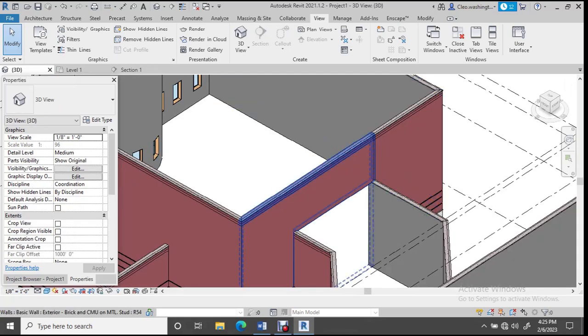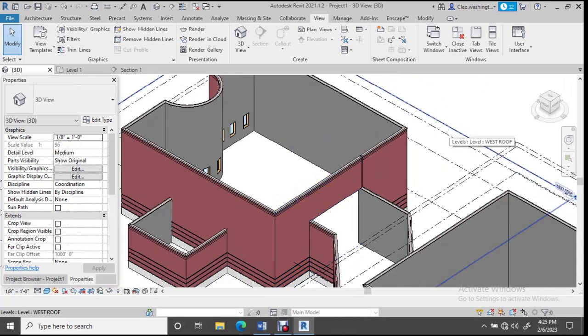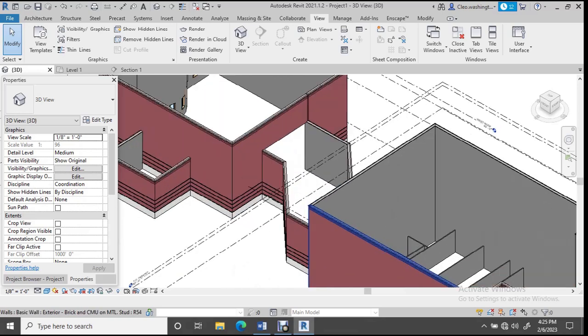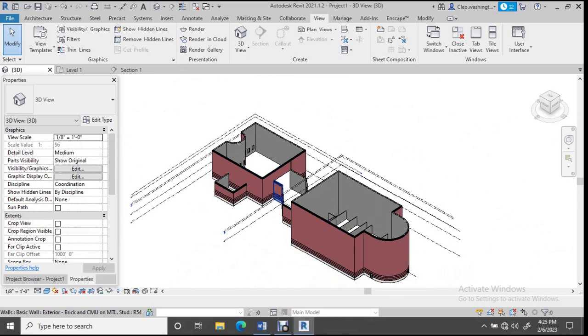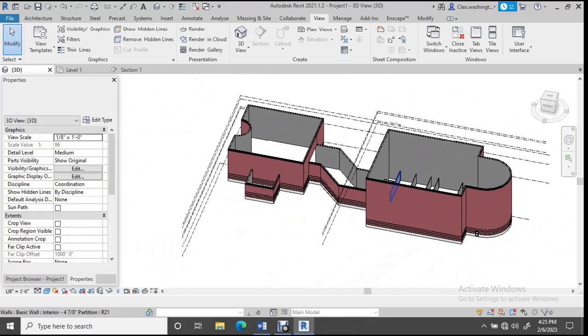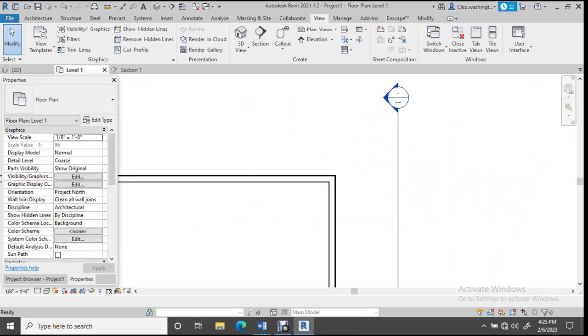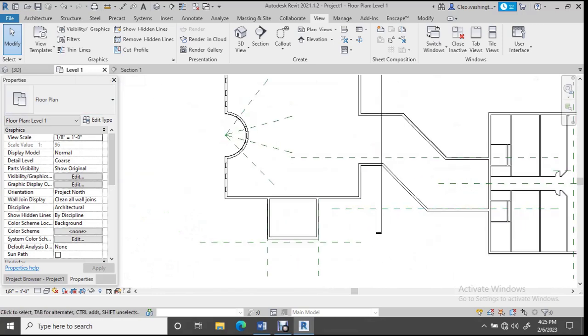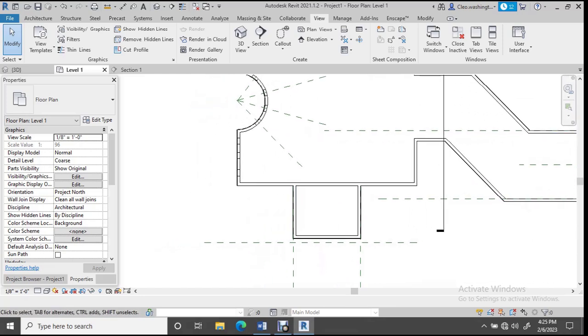And you go to your 3D model, you can see that it looks just like that. Okay, so that's pretty much how you operate Revit in sketch mode, if you want to cut holes in walls and things of that nature. Let's do another one just for repetition because we all know that repetition is your best teacher. Let's go back to level 1 and let's add a section marker right up in here, okay?